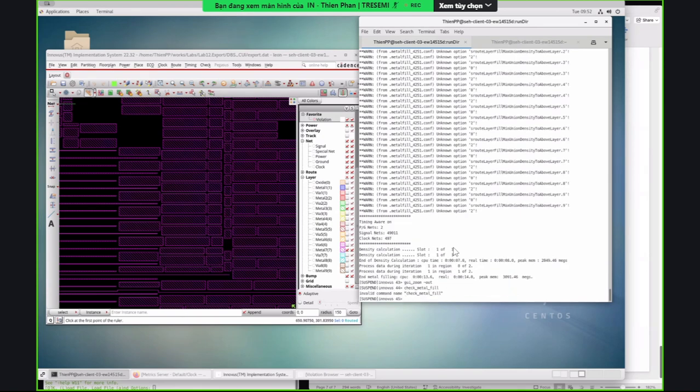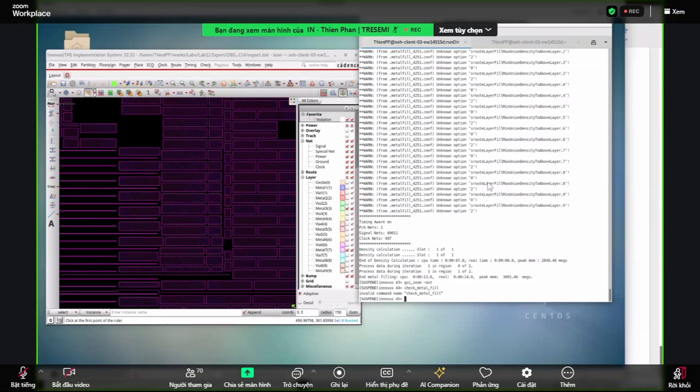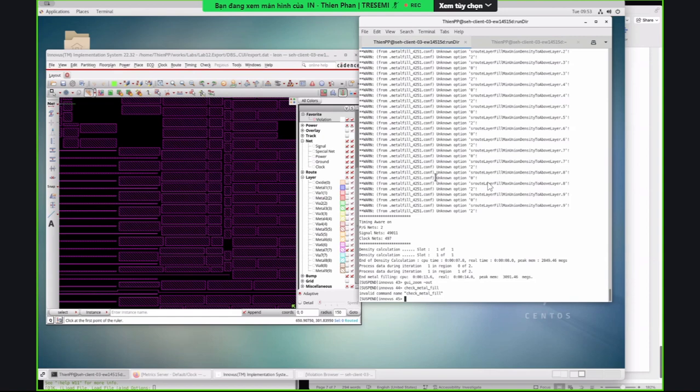So what this command does is go in and look for square boxes, and it checks the metal density within each one. It's kind of like stepping: it keeps stepping all across the die, and with various sizes, it makes sure that all of those areas meet the min and max. Did I type it when I checked metal fill? So what's the command again?